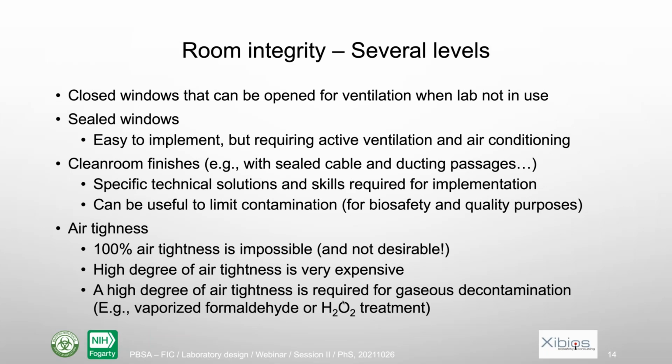But you might need a good level of air tightness if, for instance, you want to have decontamination done by a gaseous airborne system. If you want to regularly conduct some VHP treatment, for instance, in that case, you will need some high degree of air tightness just because you don't want to send that nasty chemical into the other rooms. So you might, in some case, if, for instance, the risk assessment shows and indicates that you need some frequent H2O2 VHP treatment, in that case, you will need some high degree of air tightness.